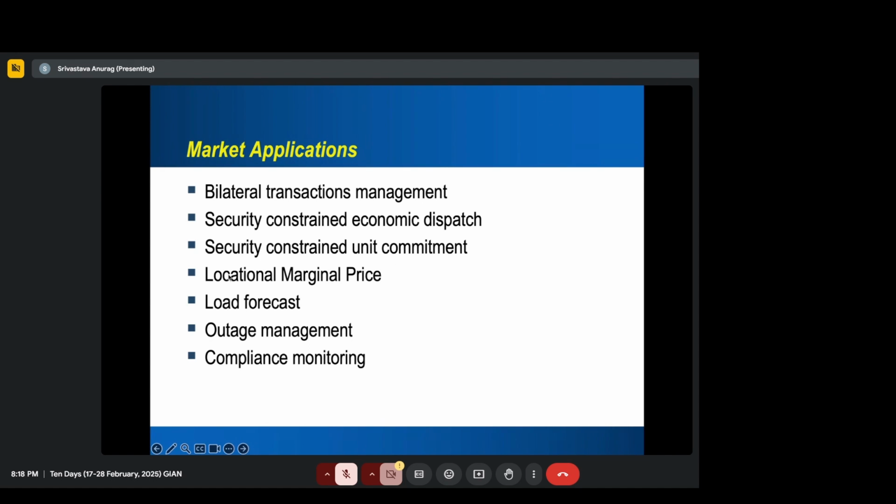Now the cost at each node is going to change. That's the biggest difference with the market. So before, cost would give the price at each node the same. But in the market, each node in the transmission system or even distribution, if you have a distribution market, which right now does not exist, research exists though, the nodal cost will be different in a market, and that depends on the congestion on the line.